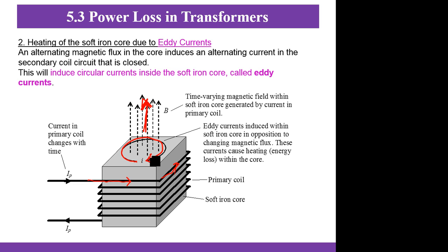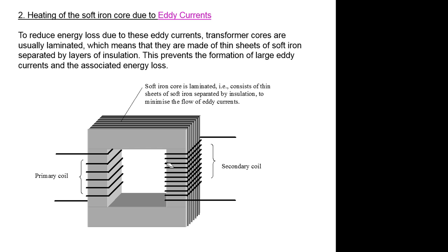So we want to prevent that from happening. What did the smart scientists and engineers before us do? They sliced up the iron core. Remember, the EMF part you cannot change, but you can change the R part. By slicing it up, previously the current went like that, one big loop. Now it's sliced up. There's a line in between them.